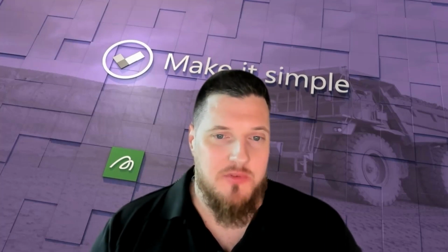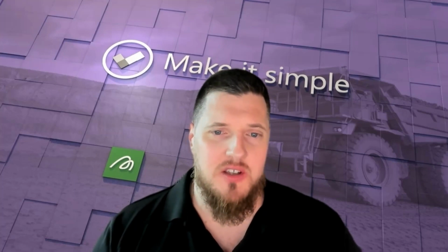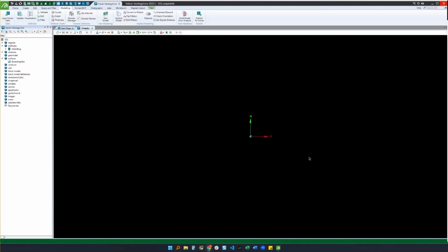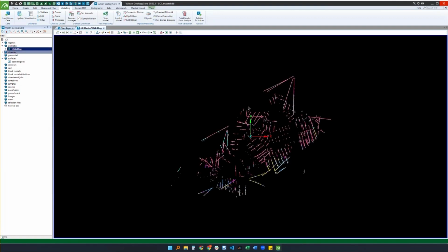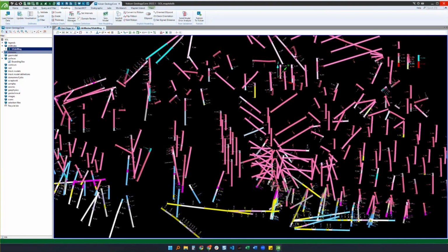So far in this series, we've already taken a look at the vein modeler and domain MCF, so in this video, we're going to focus on the implicit modeler. Since we've already covered the domain manager in a previous video in this series, I'm going to start today with a drill hole database that I've already processed through the domain manager, and I'm happy with how my domains have been flagged. In this instance, we're looking at a lead zinc deposit, and our main unit of interest here is this pink LMS unit that you can see most predominantly in my drill holes.